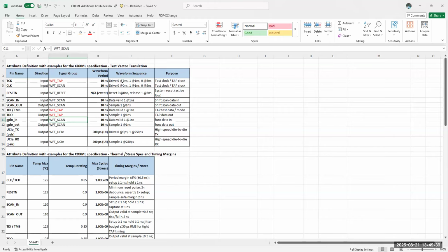Okay, yeah, the waveform will be based on this sequence, right? Whatever sequence we specify when we do the vector generation or the translation. Vector generation can apply a clock period, for example, and translation can follow the same thing, or it can even override to downsample or go to higher speed. Vector translation has that feature. But this is the spec, right? Let's say I delivered the scan pattern for 100 megahertz, and on the ATE I don't find that my patterns are able to shift at 100 megahertz.